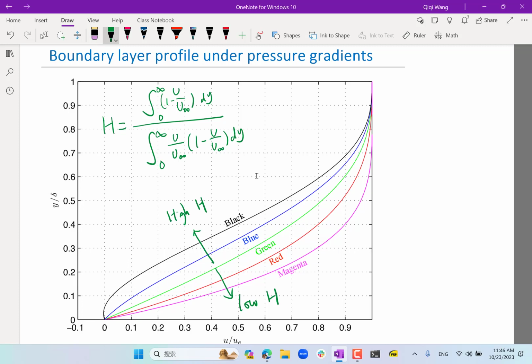Don't you need at least 2 different points of velocity to really know the pressure gradient? How are you determining the pressure gradient just from the velocity at one point? Right, so I would need the velocity outside of the boundary layer at 2 different x locations to know the pressure gradient. That's correct.